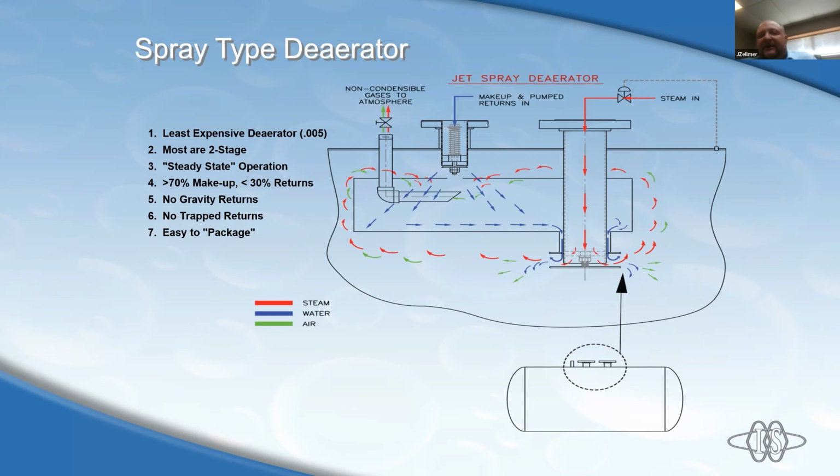This is why it is very critical, and you will see on every deaerator that it has a steam plume going out. Typically, you'll see a 4 to 5 foot plume. It may look like in the dead of winter that it's a ton of steam. In actuality, we have a pre-drilled orifice in there, so you're losing approximately 1/2 of 1% of the steam usage per hour. We're basically just letting enough steam out to know that we're getting our non-condensables out of the deaerator.